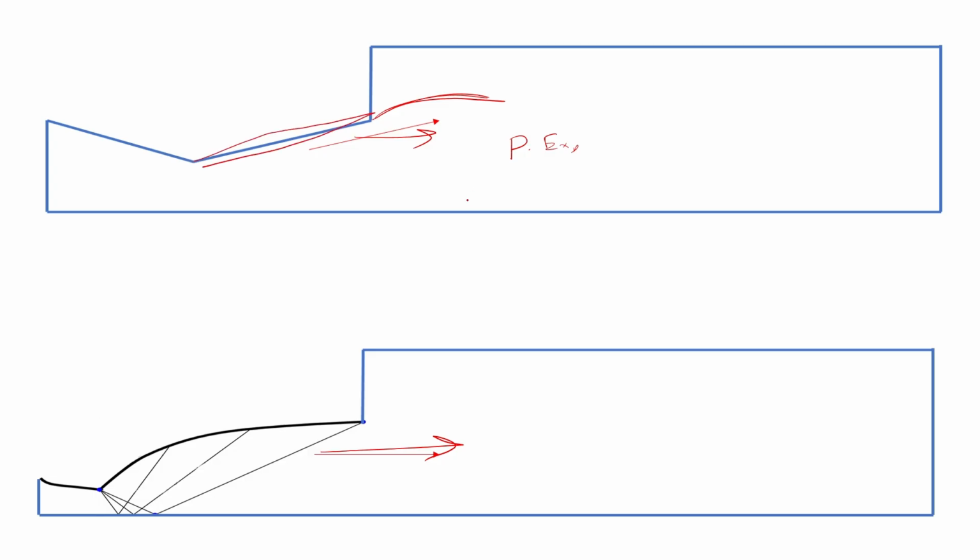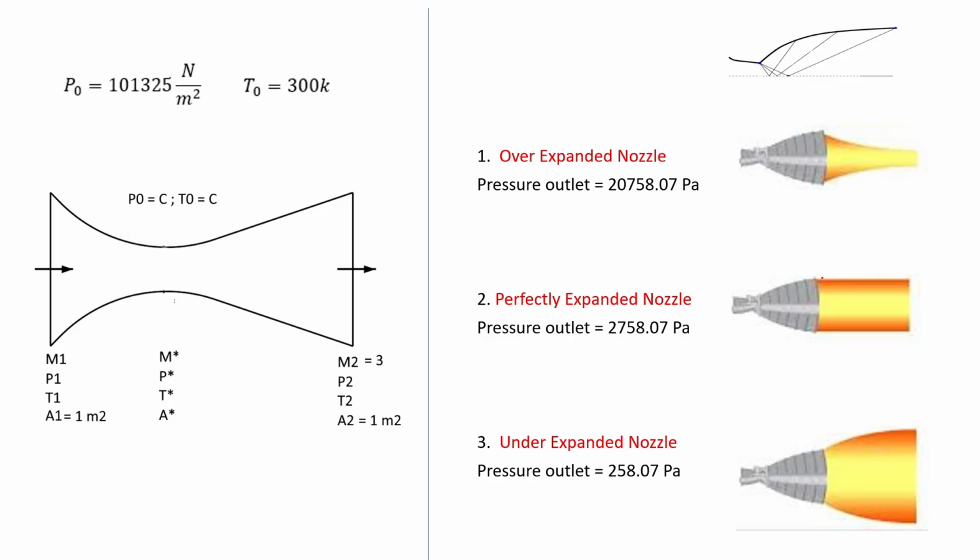So in the perfectly expanded case I may not get this kind of parallel lines, because my nozzle is like that. I won't get a parallel horizontal line like this. There will be a small expansion in the results. Okay, so instead of that straight line, if I take the contoured nozzle with the exit aligned with this flow direction, then I may get this kind of parallel jet without any shock. Only that it will differ.